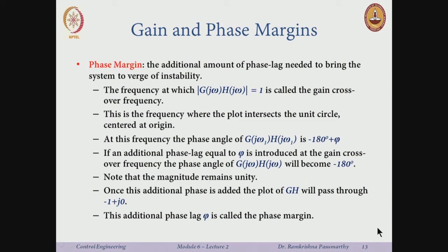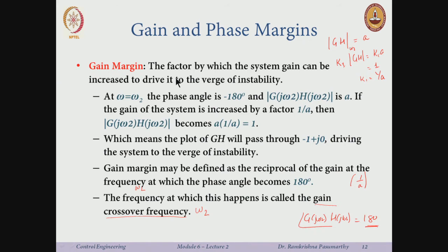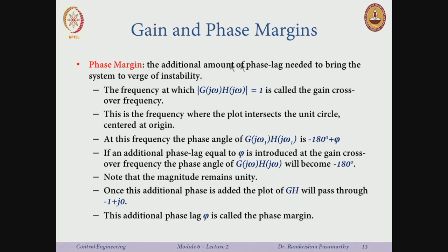Similarly, the phase margin. We could just say, now I understand gain margin, so phase margin should still be the same, right? Some similar definition. You say, the additional amount of phase lag needed to bring the system to the verge of instability. Well, this is vaguely true, but we need to be a little more careful in formulating the statement and getting the exact value. So we will see what those steps are.